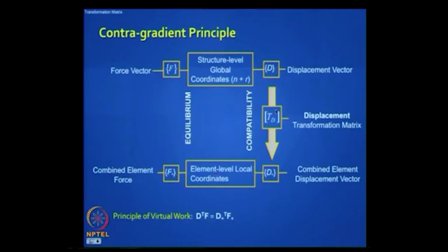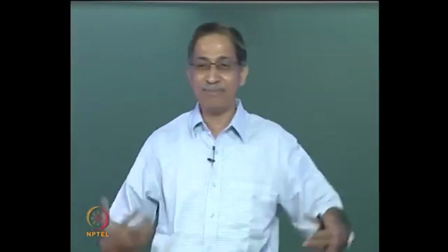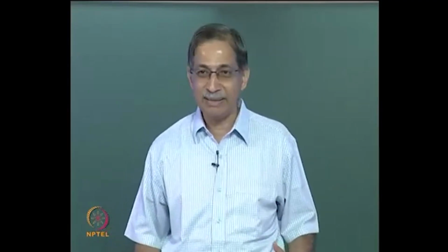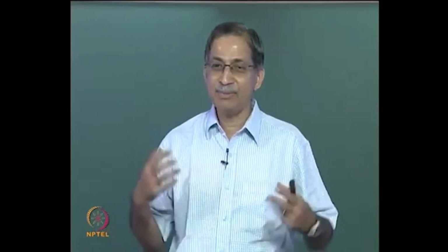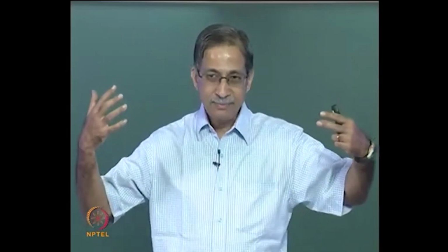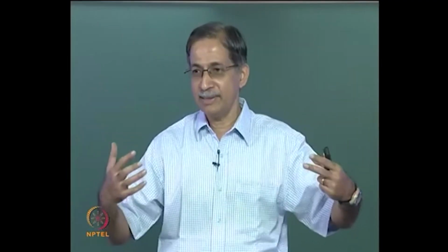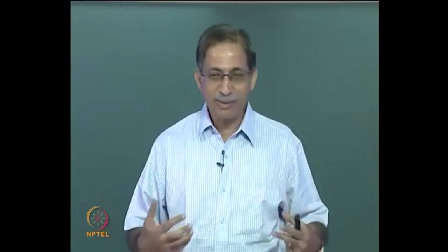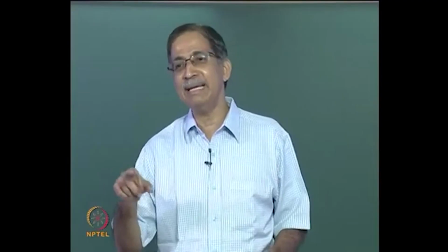So you use the principle of virtual work. You realize work is that principle which ties together the force field with the displacement field. The principle of virtual work says the total external virtual work product is equal to the total internal virtual work product. Now here all the forces are real, all the displacements are real, but the product is still virtual because I am not applying any factor half. I am just taking the forces.